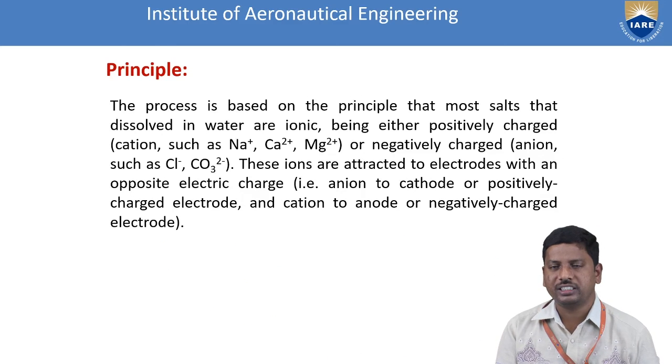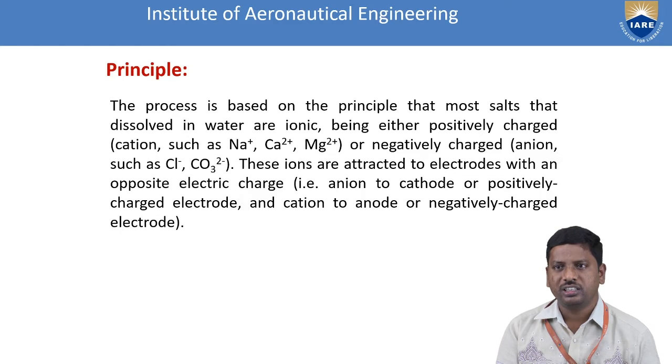Let us see what is the principle involved in electrodialysis. The process is mainly based on the principle that most salts dissolved in water are ionic, being either positively charged cations such as sodium, calcium, magnesium, or negatively charged anions such as chlorides and carbonates. These ions are attracted to the electrodes with an opposite electric charge, that is, anion to cathode or positively charged electrode, and cation to anode or negatively charged electrode.